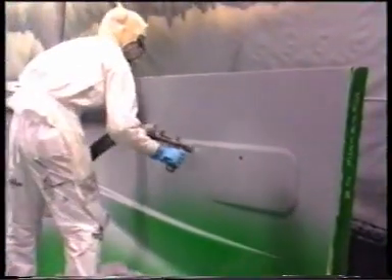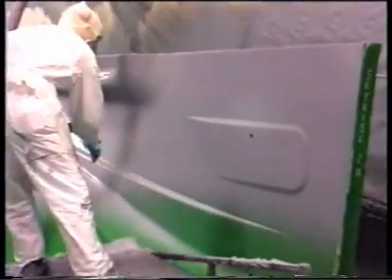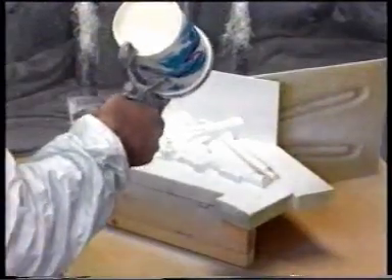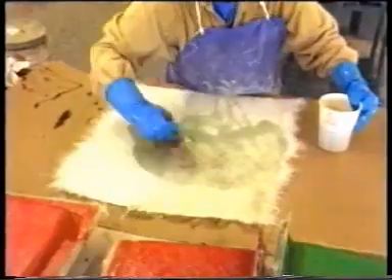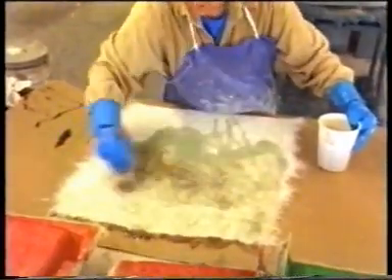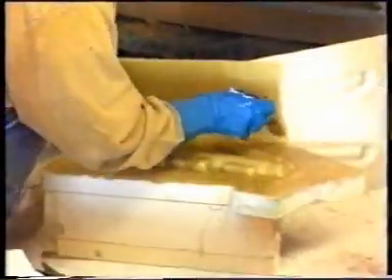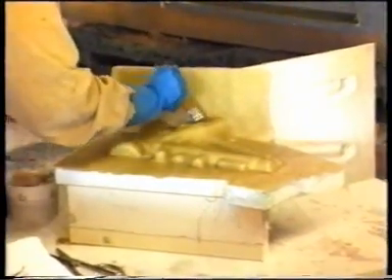Once coated with a release agent, a layer of resin called a gel coat may be applied to the mold and allowed to cure to a tacky state. As the gel coat cures, the reinforcement material is prepared for application by impregnation with wet resin or matrix material. The impregnated reinforcement material is then placed on the coated mold surface and hand-rolled for uniform distribution and removal of entrapped air.